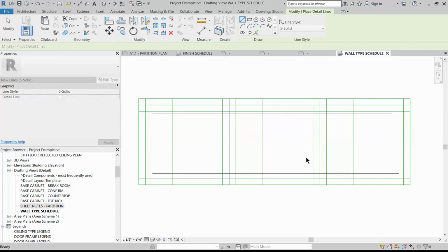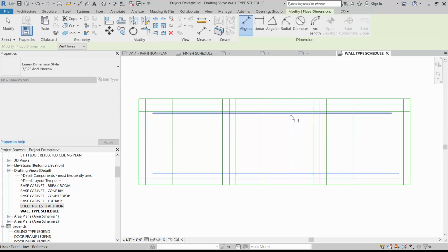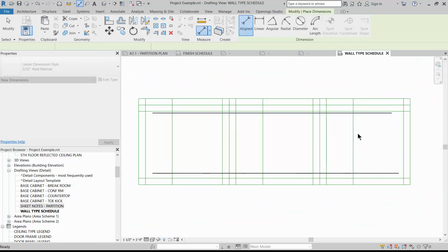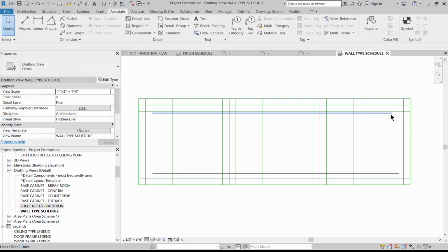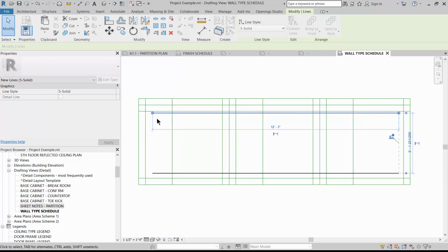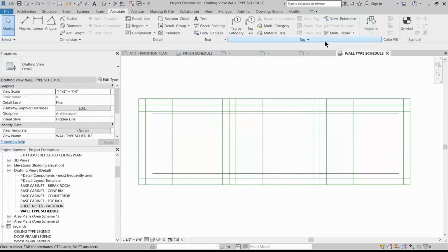I'm going to draw the line for the underside of the deck. Now keep in mind, this is not to scale. This entire distance in this particular view is only about 3 feet, where in reality you probably have something like 12 to 14 feet between those two. So we're going to utilize a break line because this distance is not to scale. And then we also need to use one more detail line to denote the height of the ceiling.